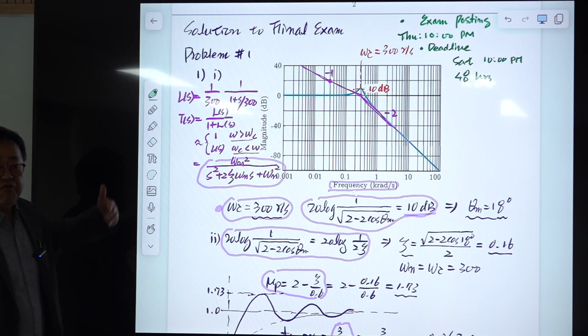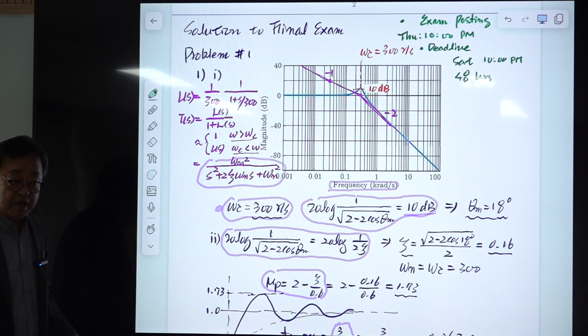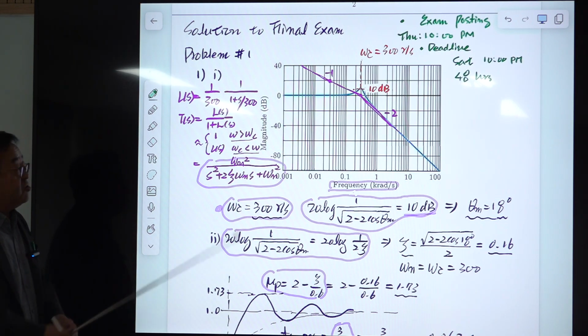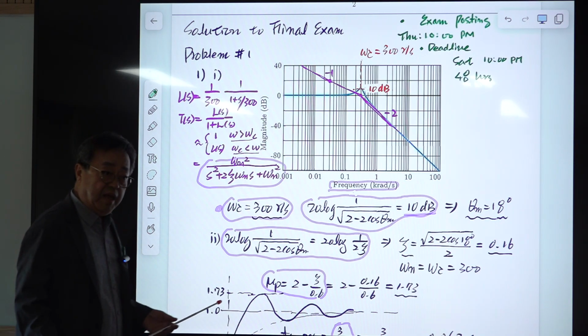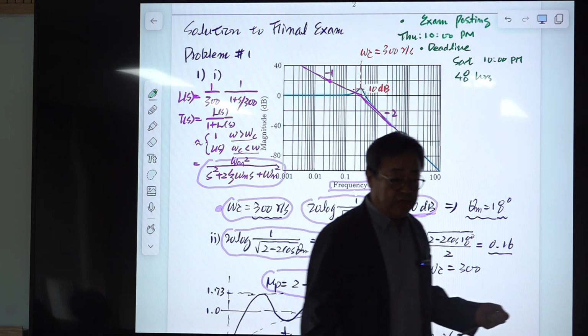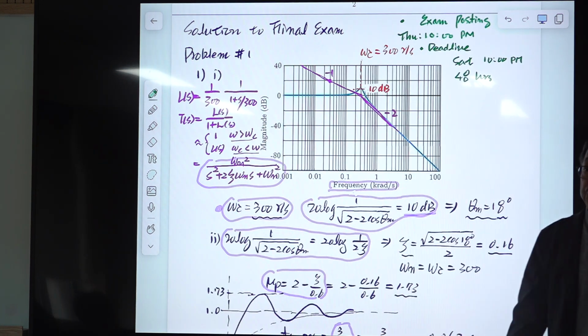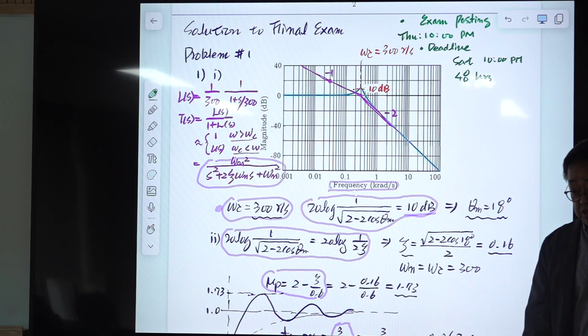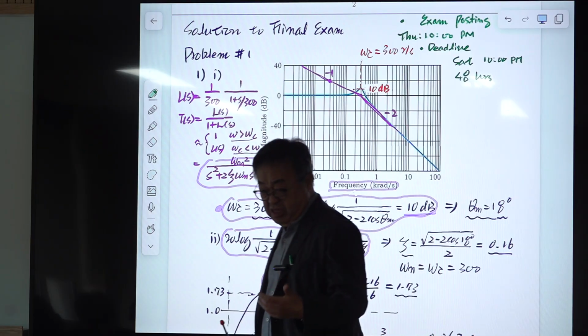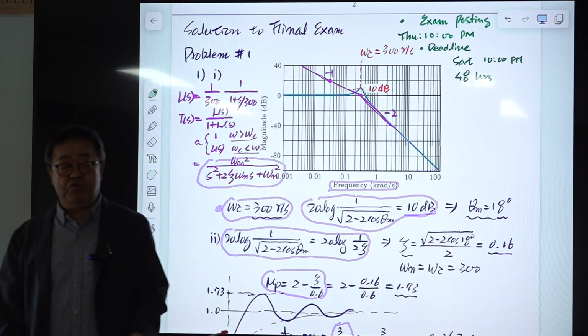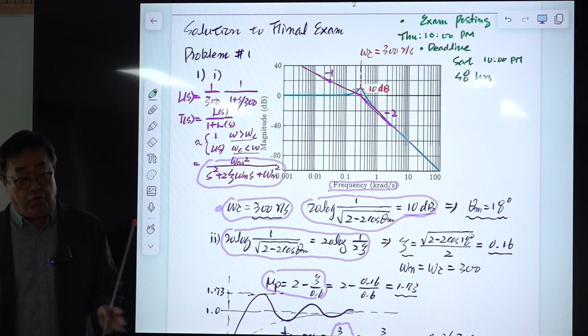If you see this problem first, you may wonder how this is related to the loop gain and phase margin of your system. But every hint is here. This is the input to output transfer function, so we are using the concept and the term of equivalent second order system. We are saying that every feedback system can be simplified to an equivalent second order system. In that, we are talking about only input to output transfer functions. Disturbance to output transfer function is an entirely different story, and you need other skills.